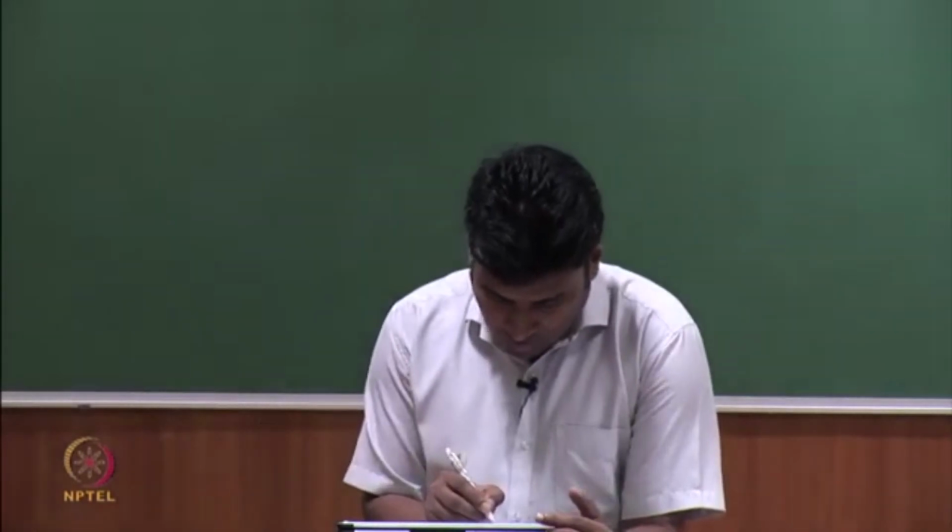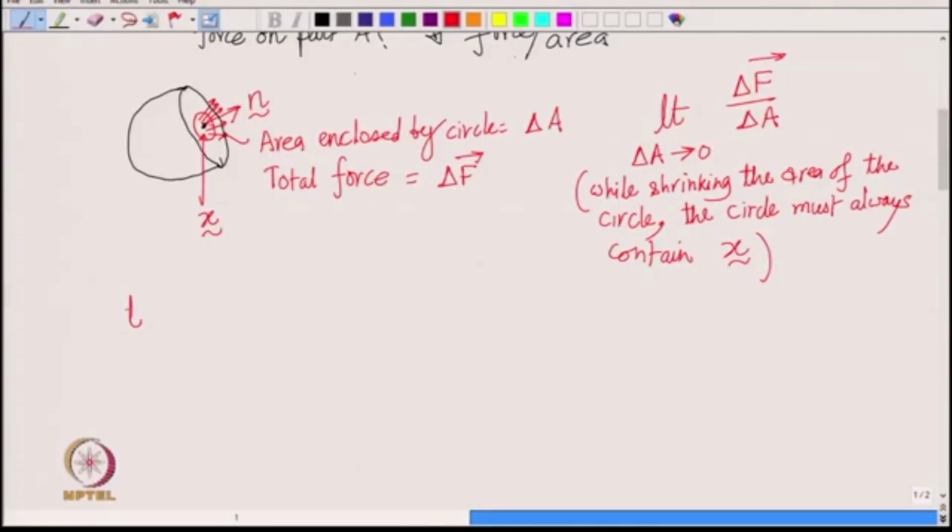Okay. So, I am going to denote traction by the vector t, again with a tilde because it is a vector, and then I have to say at which point I am measuring the traction, that is the point x. So, traction at point x, it depends on what point, and it also depends on what plane, so the normal to the plane n.